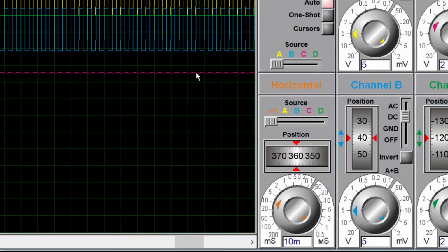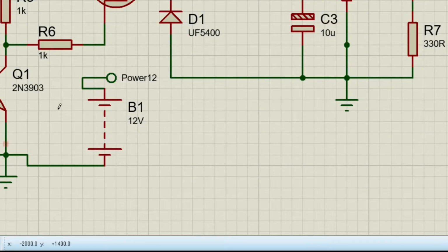You see the output voltage in red now. I will take it to ground, so you can see now this is the ground, and this is our output voltage. It is 2.5 divisions, and there is 2 volts per division, so we are at 5 volts, as this DC voltmeter shows here. So we achieved what we wanted by switching the circuit at 200 Hertz.